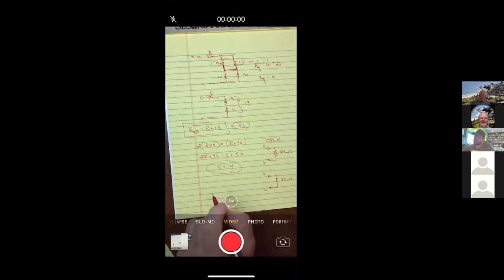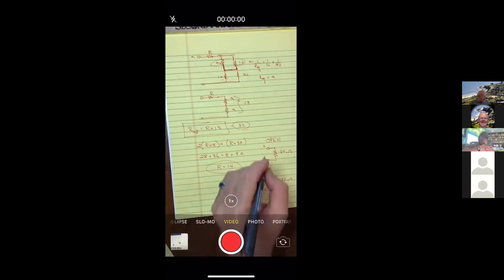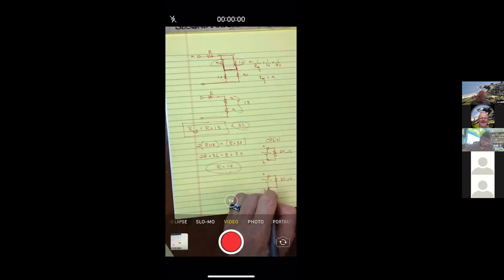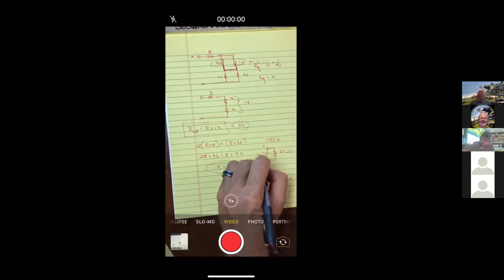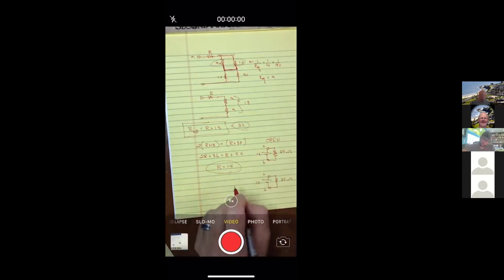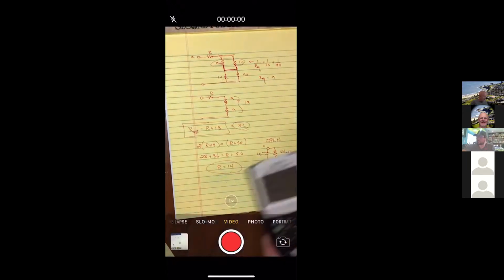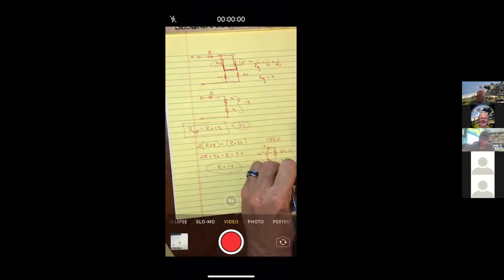Okay, and I might have confused you, because if I had hooked this up, let's say this was, I used the dashboard on a car. So let's say this was actually hooked to 12 volts. When the switch was open, I would have 12 divided by 64, and there would be 0.1875 amps flowing through.